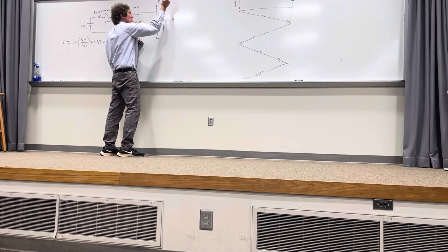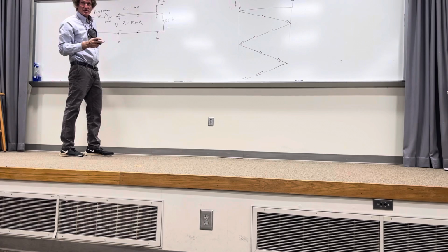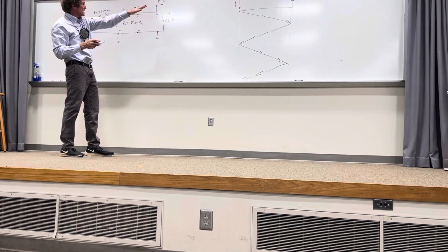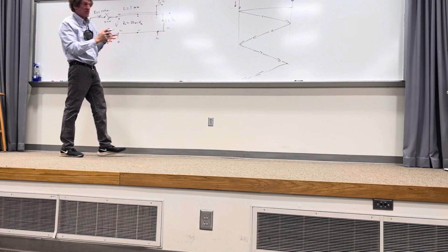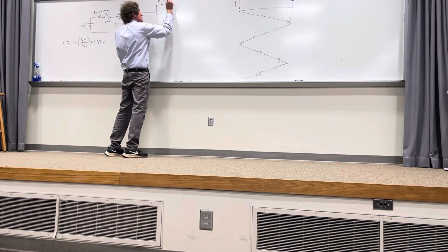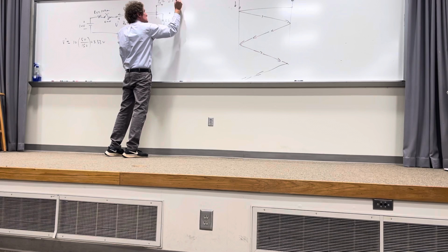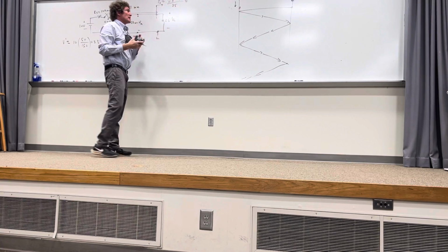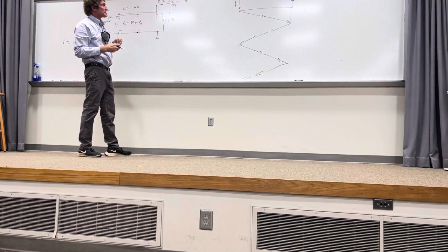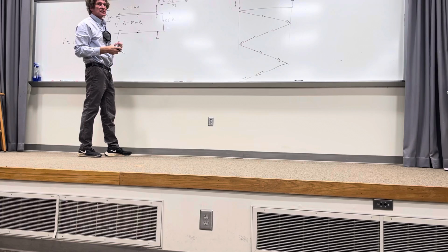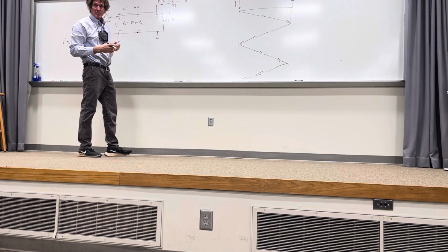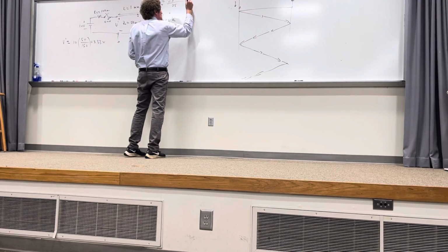Okay? Now we get the values that we need for the reflection coefficient. The reflection coefficient at the actual load is equal to what, guys? Well, it's going to be Z load minus Z naught, correct? So it's going to be 25. It's always the impedance you're going into, which is the load impedance, minus Z naught, which is 50, over the two added together, which is 75. Now that's going to be 25 minus 50, which is minus 25, over 75, which is minus 1/3. Do y'all agree with that? So this is minus 1/3.